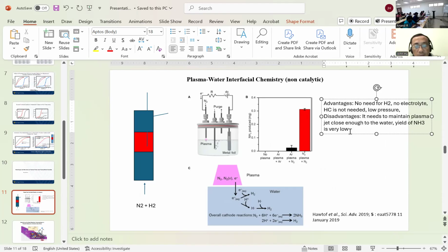I think this one also wastes a lot of nitrogen. I don't think this is batch operation. Did you see the nitrogen coming in? They have a purge and the gas coming out. I'm glad we did the exercise on calculating conversion. If the data give you 5% ammonia, your conversion is somewhere close to 10%.